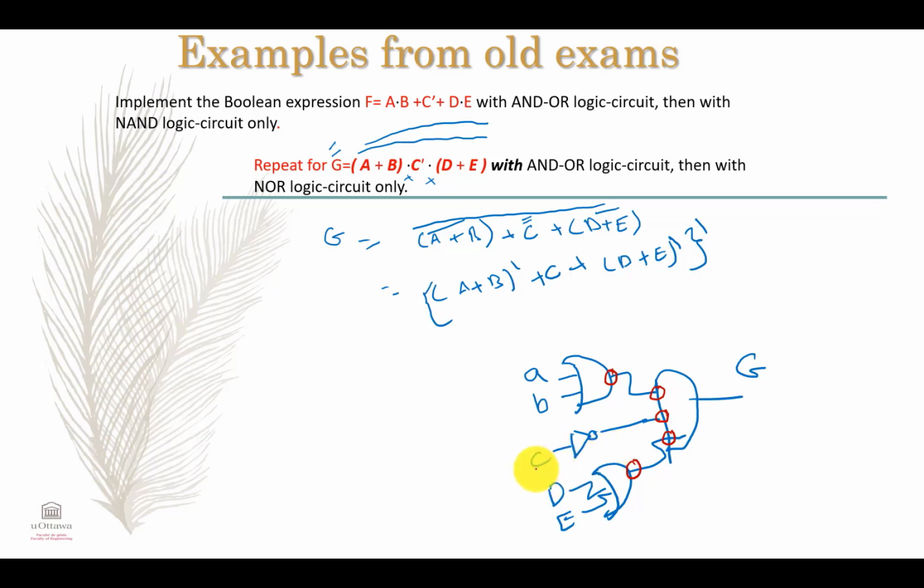So basically, I have to pay attention to C, because here it will be C prime, and then C prime, I have to have it like this. So what I have to do is to pay attention to this one, okay, so to remove it. Now this logic diagram is basically an OR, and this one is basically an OR, and this one is a literal, so itself, so it's gonna be C.